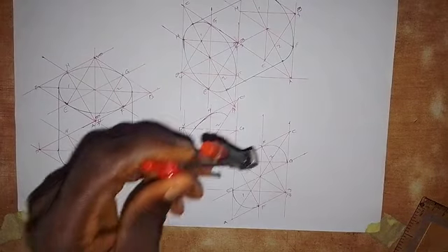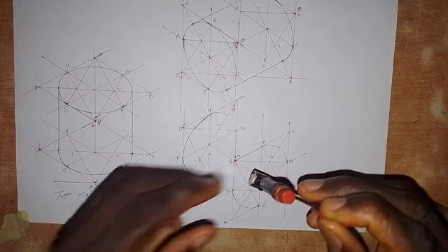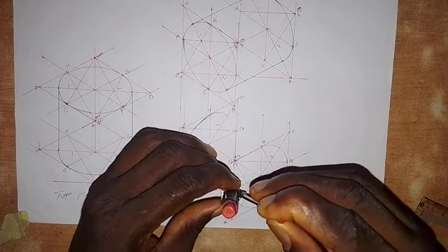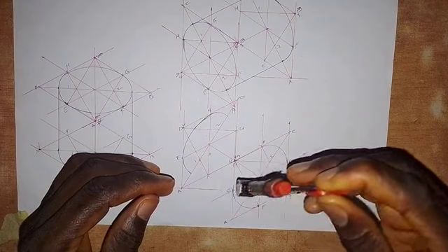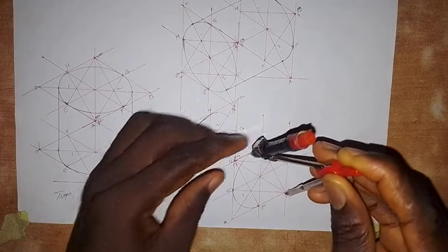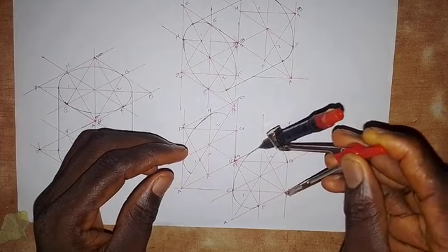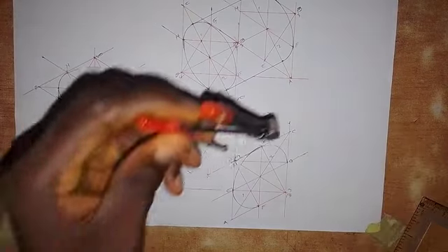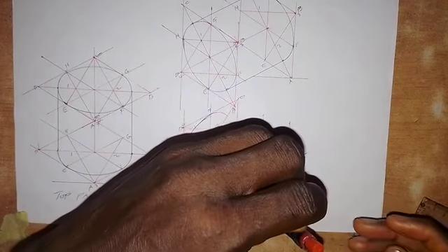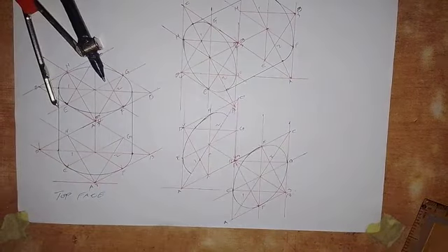Okay, so then we put at center 3. This is center 3 here. Extend it to point E here. Then we draw an arc from here to touch point H here. The compass has adjusted. Okay, touch this point. We have it here. Then we put at center 4 to touch this point F here, and then we turn it to touch this point. Alright, so we have the circle drawn.